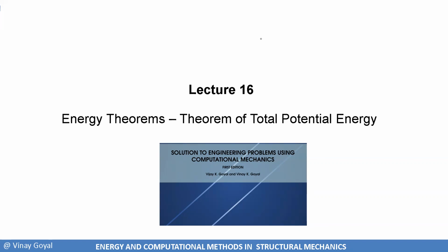We discussed the idea of the Green-Lagrange strain tensor, which is for large deformations, and we also discovered that for small gradients, the Green-Lagrange strain tensor can be simplified to the infinitesimal strains. And from there, using the idea of incremental work done, or the principle of virtual work, we demonstrated that the stress must be somehow related to the strain.